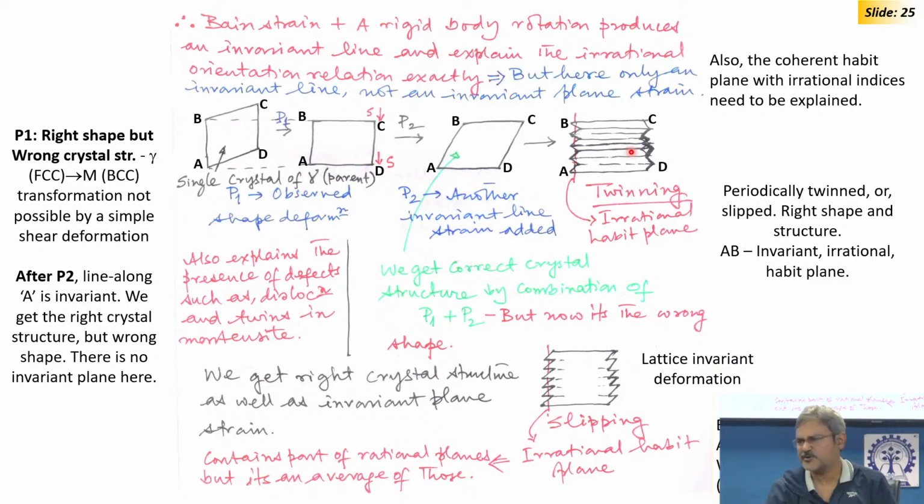Twin of course produces an interface, and by microscopy people literally see that in the martensite plate either there is twin or there is dislocation slipping at the edges. So, these things really happen, that is proved. A lot of controversial different theories are there. Some theories say that they take the hard sphere model, take the orientation relationship and the symmetry, and they say the glissile interface may not be required.